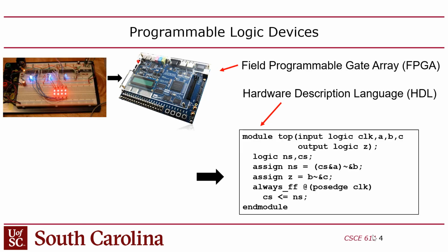So how are we going to do it in this class? Well, instead of the breadboards, we're going to use these FPGA boards instead. An FPGA is essentially another form of a breadboard, basically. But instead of having to plop chips down into it and connect wires, it's a chip that can be electronically programmed to behave as any arbitrary digital logic circuit. So it's like having a breadboard in 7400 series chips that is electronically put together by a robot, except it happens inside the chip on that board. That's basically what an FPGA is. It stands for Field Programmable Gate Array. It's a programmable logic chip.